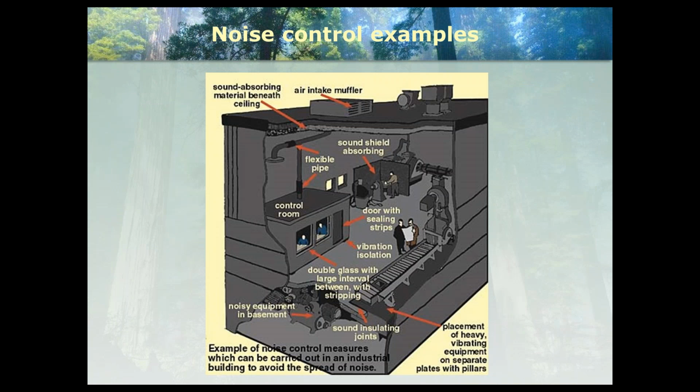Noise is another big one where we always want to strive for engineering controls. A lot has to do with air intake. Air is always loud, and we'll get into an example later on. Can we put our air intakes on the ceiling, or put loud compressors in the basement? Looking at that, we don't want our workers right next to loud equipment if we can help it.